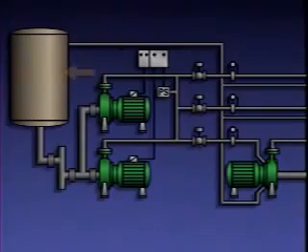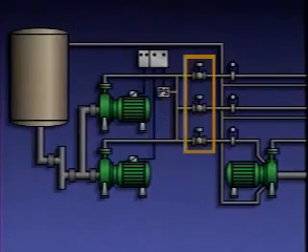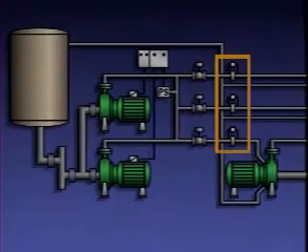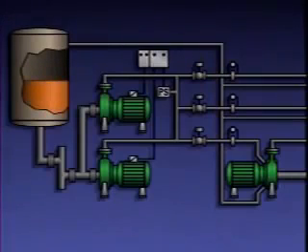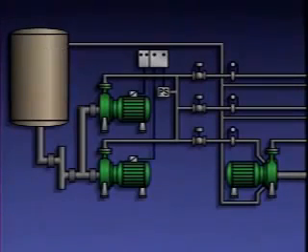The system consists of a storage tank, a filter, a supply pump and a backup supply pump, a low pressure switch, a pressure regulator for each mechanical seal, and a flow meter for each mechanical seal. For this process, an oil is used to lubricate the mechanical seals. During operation, the supply pump draws the oil from the storage tank through the filter.